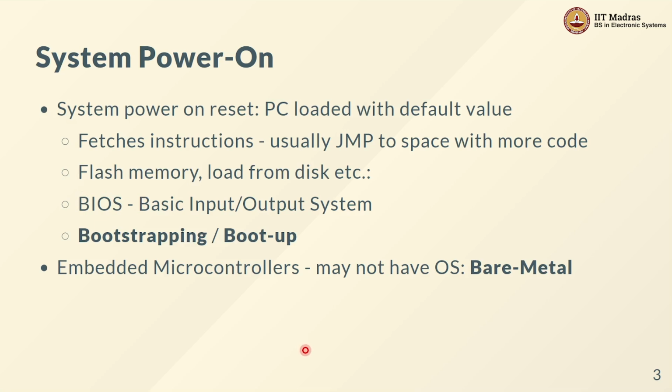What happens is the manufacturer, the person actually building the CPU board for you, the motherboard, is going to put in some set of instructions and wire up your entire processor and everything else in such a way that when the address corresponding to the default PC comes out, it's going to come back with instructions corresponding to the BIOS, right? So this is in the manufacturer's control.